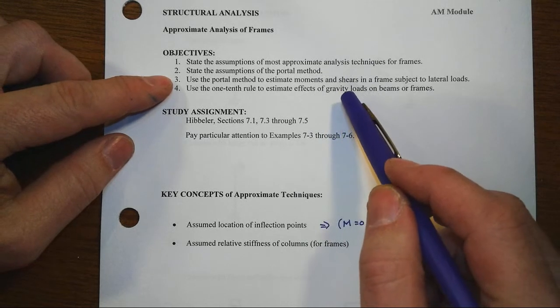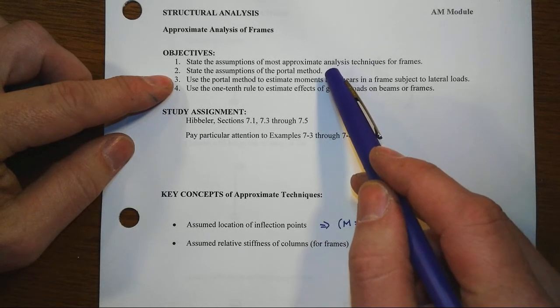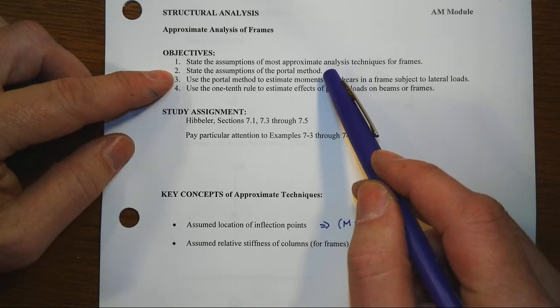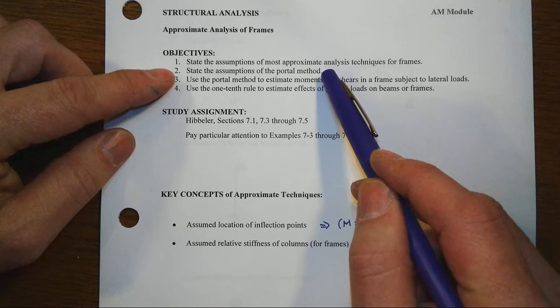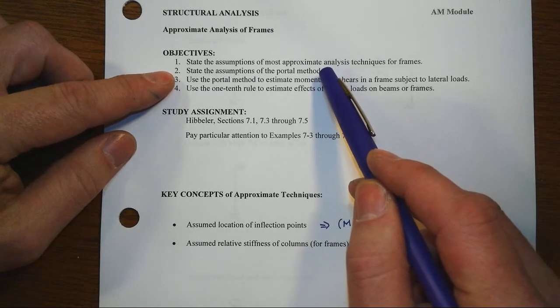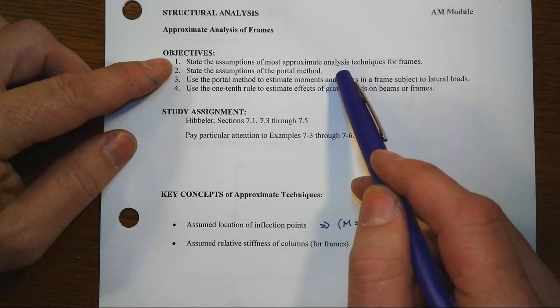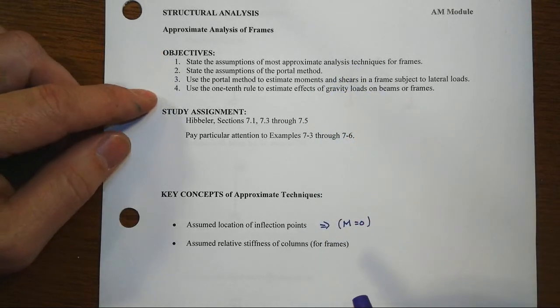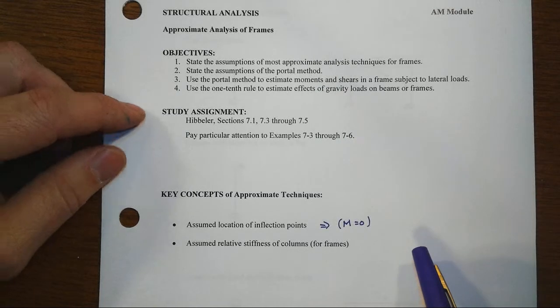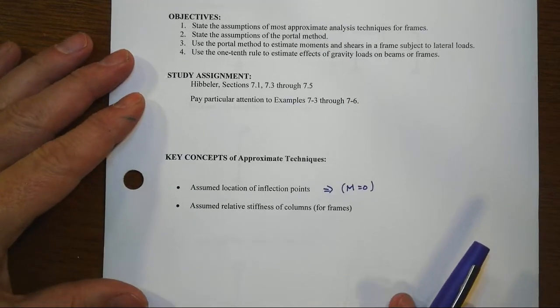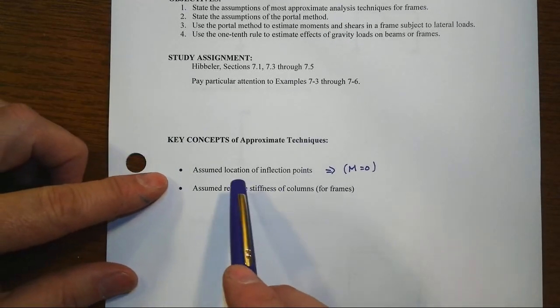We are not going to go into the cantilever method, which is a method for tall buildings, and instead we'll just focus on more conventionally relatively shorter buildings, so things that are less than 10 stories tall. And then the gravity load analysis approach too is going to be one that's useful for both beams and frame kind of situations. Right now, in both of the approaches here, the key thing is